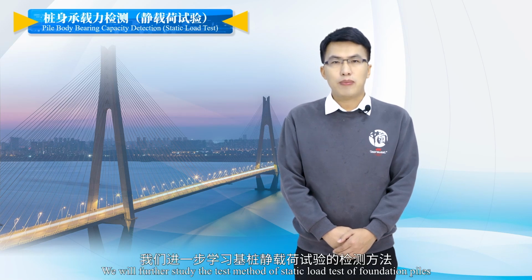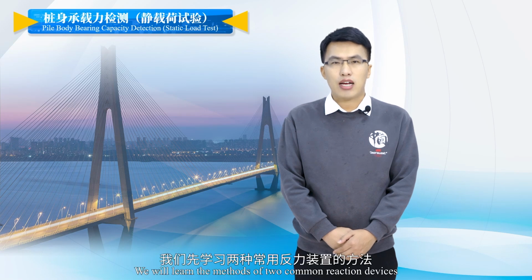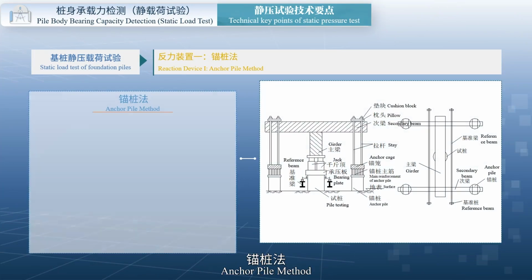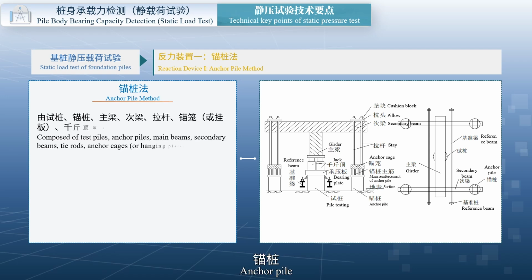After understanding the static load test devices for foundation piles, next, we will further study the test method of static load test of foundation piles. First, we will learn the methods of two common reaction devices. Common reaction device 1. Anchor pile method. Composed of test pile, anchor pile, girder, secondary beam, stay, anchor cage or hanging plate, end jacks, etc.